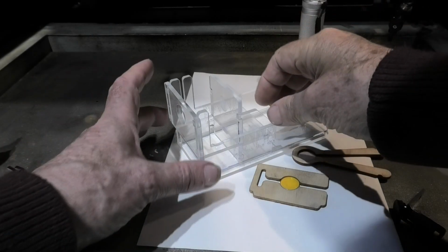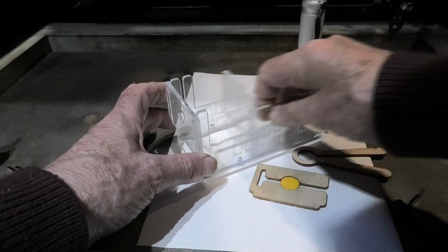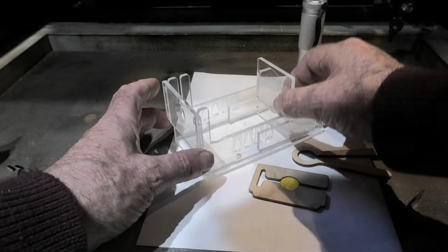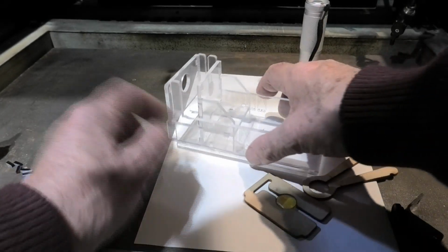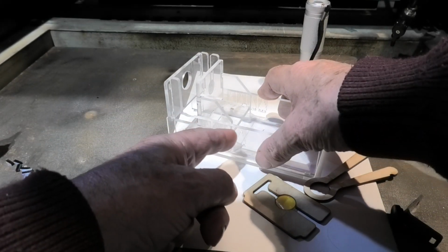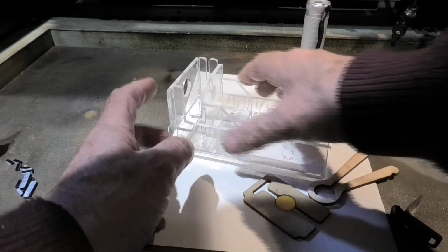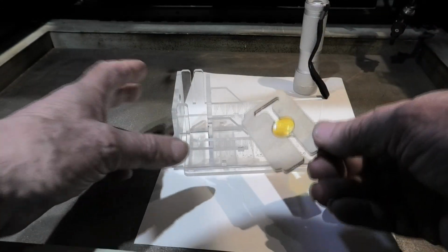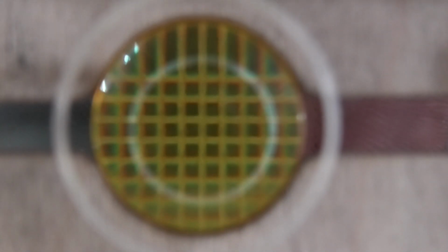trick. I have a little fixture here that I've designed that has got a little screen on it, and it slides backwards and forwards, and there's some markings on the side here which represent the focal distances of lenses. So if I pop my lens into a little holder there, I'm going to let you look through the eyepiece of that fixture, and as I move the screen backwards and forwards, you see that I'm moving the target in and out of focus, that grid.